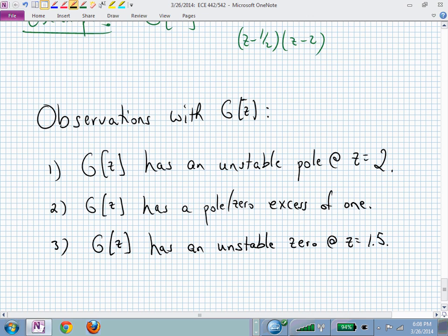It makes your job of controlling the system more difficult when your zeros are outside the unit circle. You don't need zeros inside the unit circle, but it's nice to have them there. Is that distinction clear? You don't need them inside, but it would be nice if they started there, but a lot of times you don't have a choice.